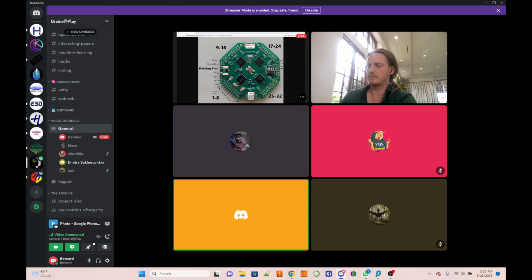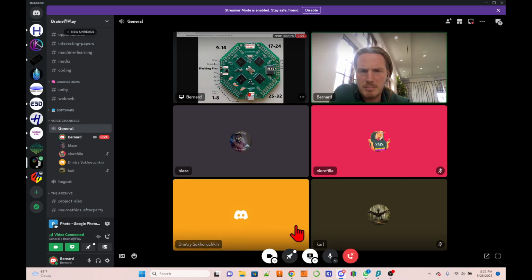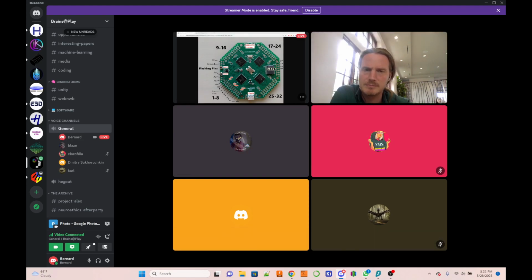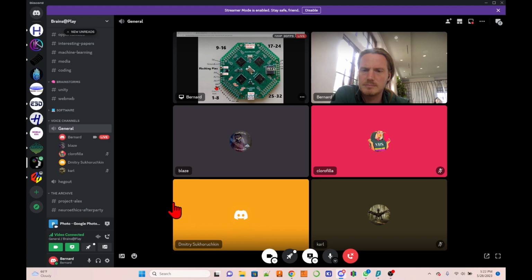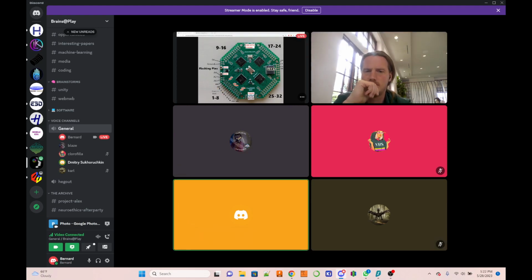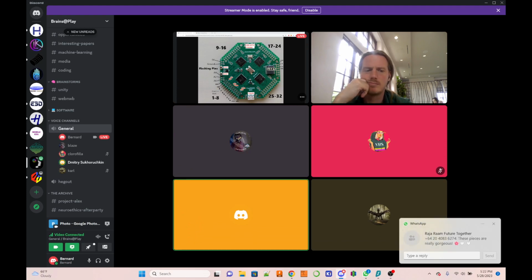Yes, this power isolator also does some filtering. I connected it right here at the USB cable. But if you connect it to 5 volts where the debugger is, it's not okay, because all the noise will be inside the board.